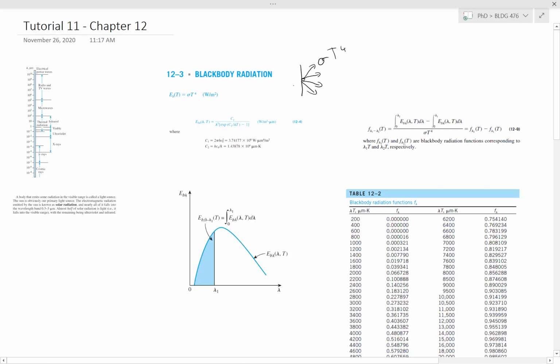And to relate this back to what we worked on, if you have another surface surrounding it, it also transmits radiation back at the surface. So often the total Q that we talk about is the Stefan-Boltzmann constant times T of our surface to the 4 minus T of our surroundings to the 4.